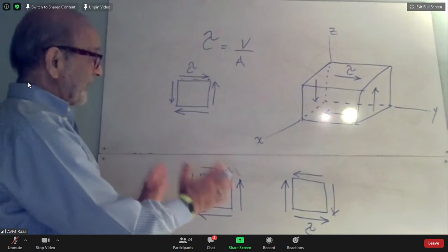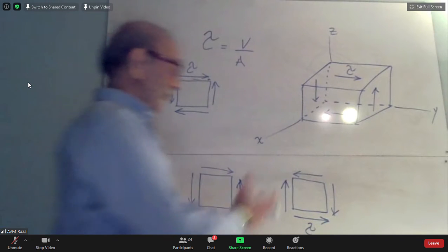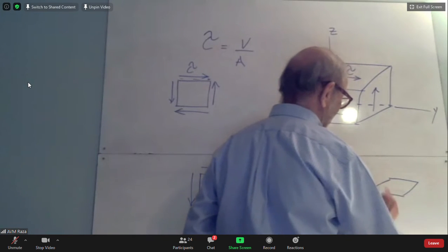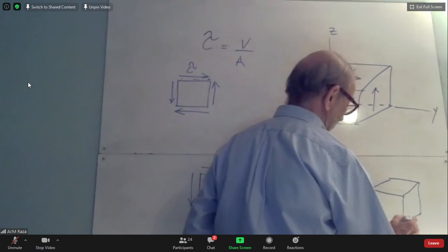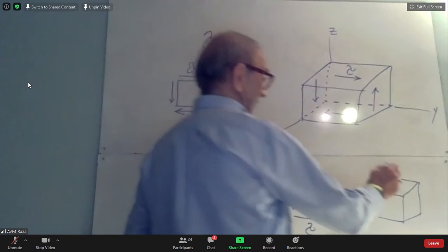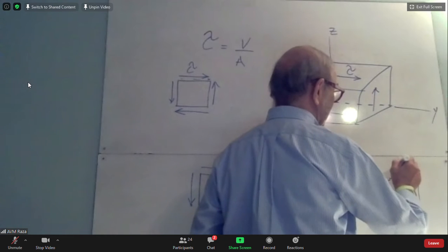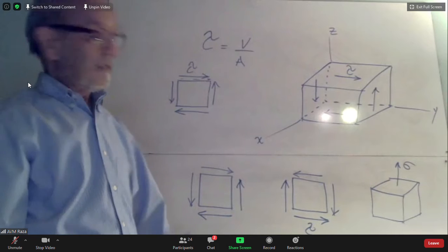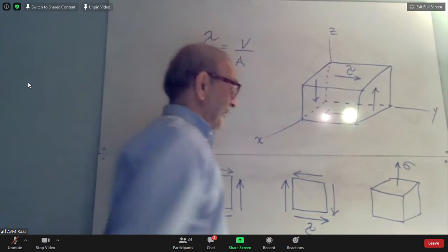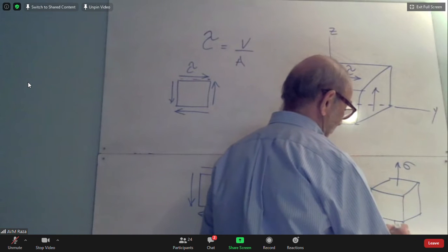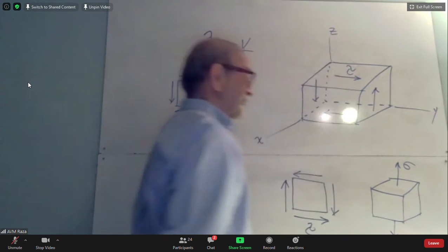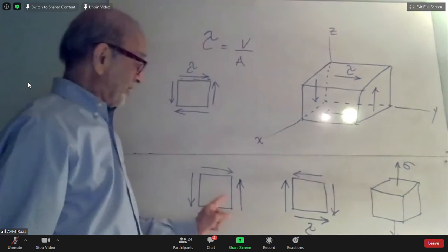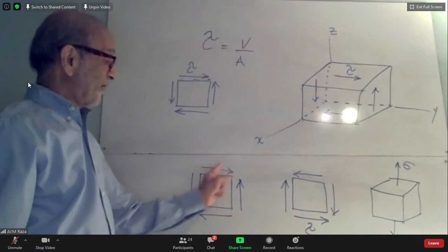By the way, it's exactly the same for the normal force or normal stress also. For example, let me show you a little cube there. If I had a normal stress there, where will I need to have a balancing normal stress? On the bottom surface, like that. So there will have to be an equal and opposite normal stress. So on the cube, just 2 will be enough for equilibrium. But for tau, for equilibrium, there are a minimum of 4.